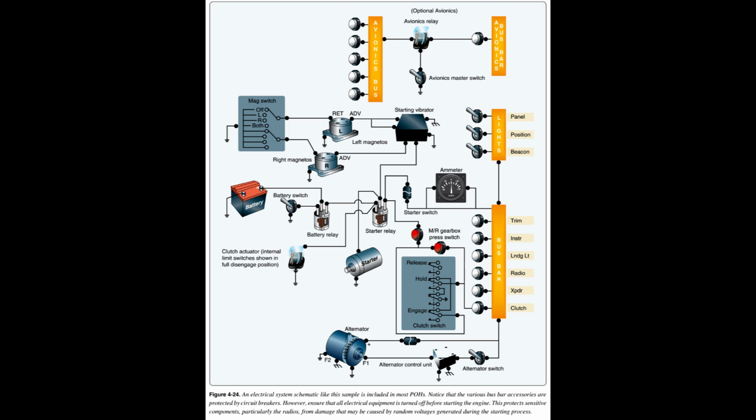needs of the system. An ammeter showing a discharge means the electrical load is exceeding the output of the alternator or generator, and the battery is helping to supply electrical power. This may mean the alternator or generator is malfunctioning, or the electrical load is excessive.